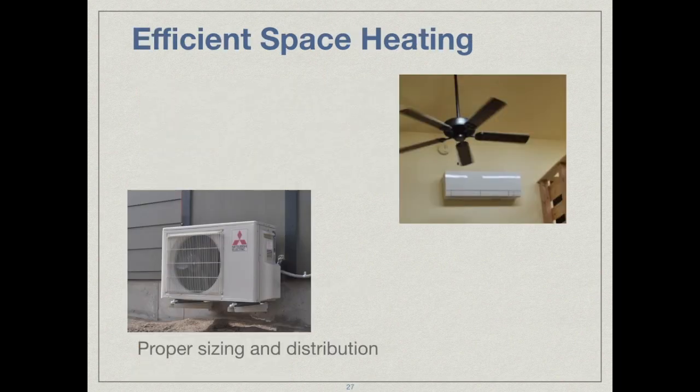When homes get super efficient, and especially if they're a little bit smaller, they have a very low heating load. That's part of the idea. Unfortunately, a lot of the conventional heating and cooling equipment out there doesn't get small enough to service these homes efficiently. You don't want a big furnace in a small house because it'll just turn on and off. That's called cycling, and it'll cycle over and over again, and that's not good for anything.